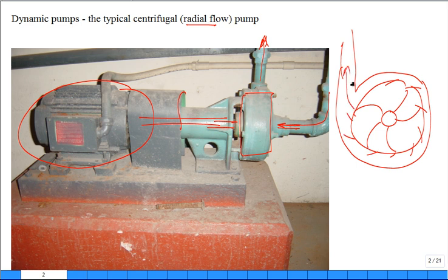It really is the diameter of this inlet pipe and the diameter of that outlet pipe. Typically the suction is a little larger than the discharge. But for first introduction, just say they're the same diameter, okay? If they're the same diameter, even though the fluid may be very fast coming right off the tips of this rotating part here, it slows down and builds up pressure, and the pressure coming out is a lot higher than the pressure going in.